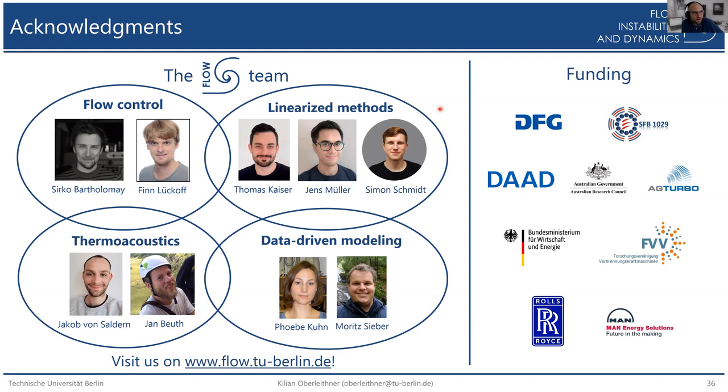And what you can also do, I mean, this is practically sometimes useful or not, you can use very simple eddy viscosity models where you relate your eddy viscosity to a characteristic length scale and a characteristic velocity. So in some cases, like in what Phoebe Kuhn was doing, she has a paper just recently published about the coherent structures in the far field of a jet, and there the eddy viscosity models are very reliable and simple.